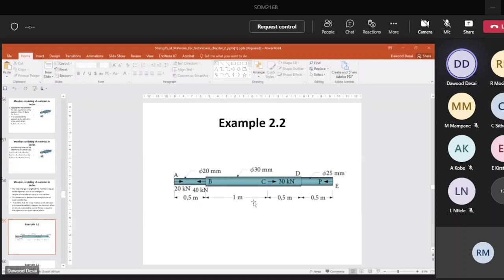Okay, that's the equilibrium thing we spoke about, summation of forces, eh? All right, you can see here this force P, you don't know it. So it's very easy to calculate that. All right, so force P now, you can see there is the summation of forces along the X direction, must always be equal to 0. Okay, so it's got plus 20 minus 40. Now, let me explain that to you. How do they get plus 20?